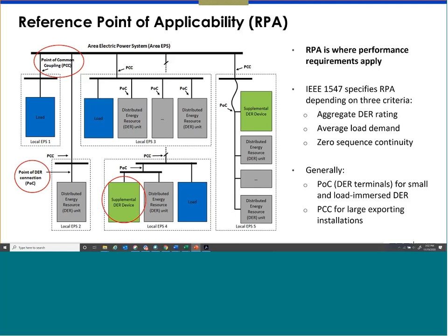On the other hand, if it's a larger facility, larger than 500 kW, even if the load is less than 10%, or it's just a pure generation source, say 1 megawatt, 2 megawatt, a solar garden. Many of you have those types of facilities, 1 megawatt, 2 megawatt, pure generation facilities. For those kinds of things, the requirement will be at the PCC, which in most cases is the metering point where it hands over from the customer to the grid. So those are the very nutshell, higher level differences, but there are a few more details in this standard.